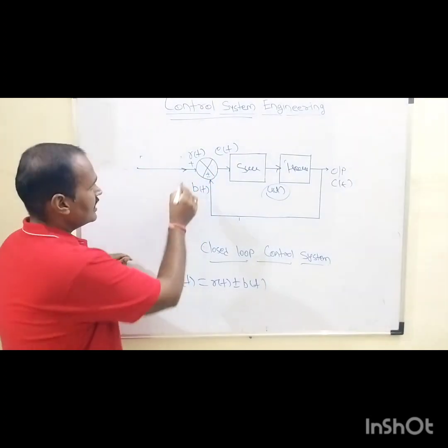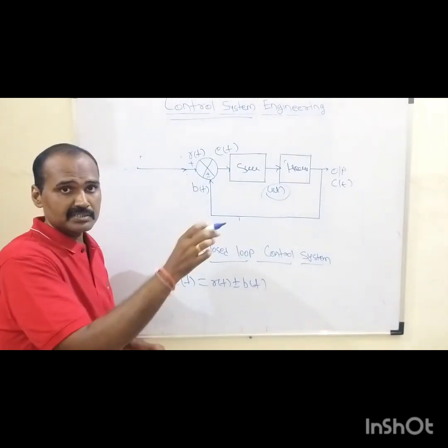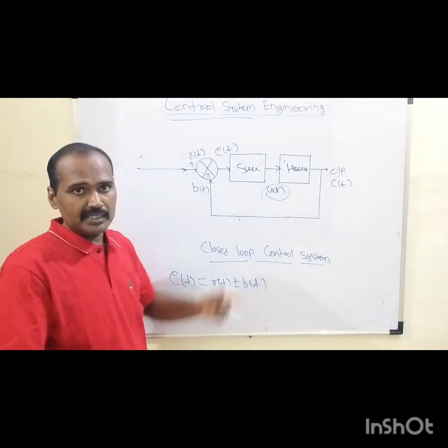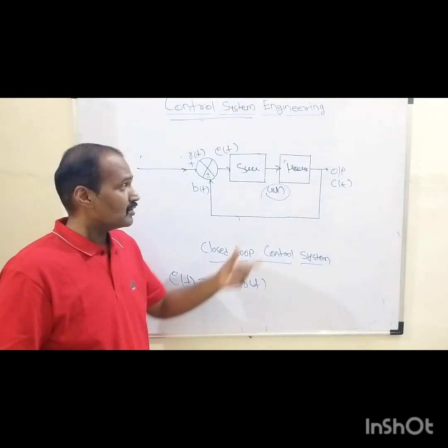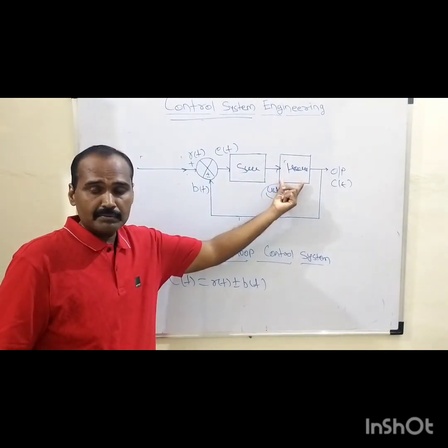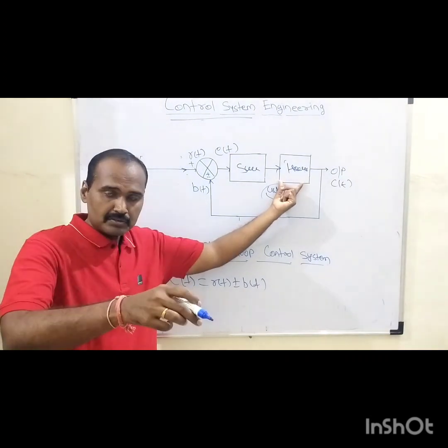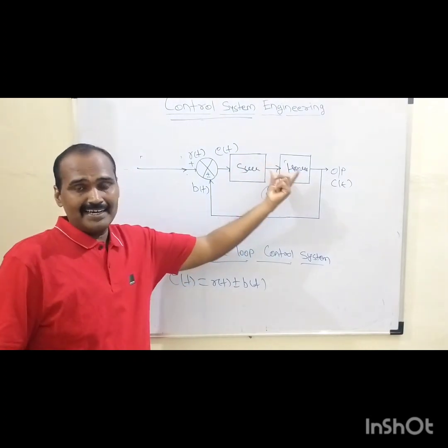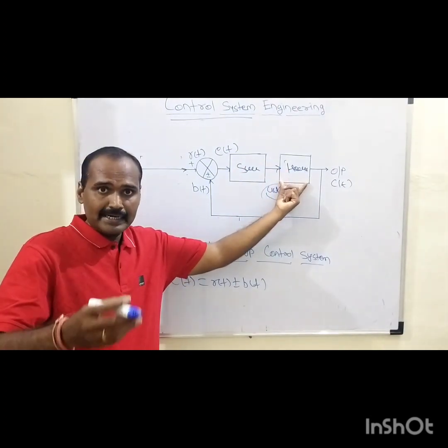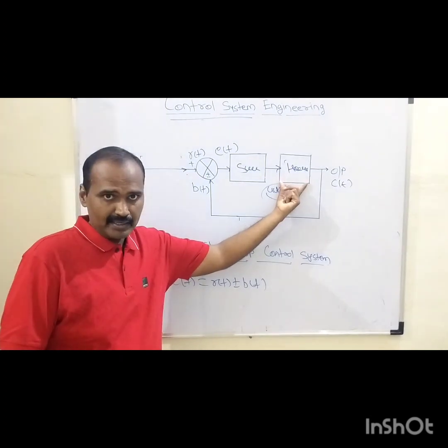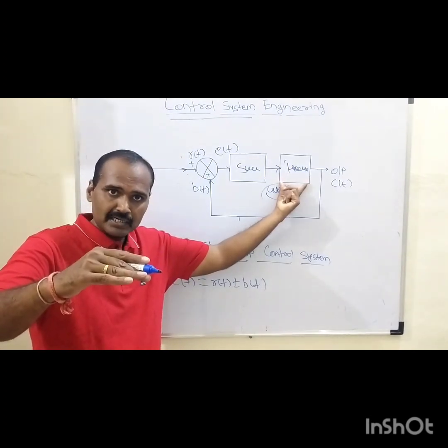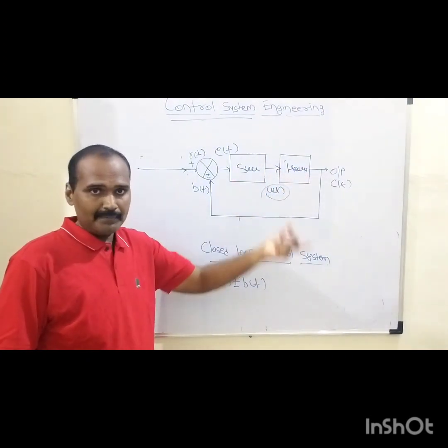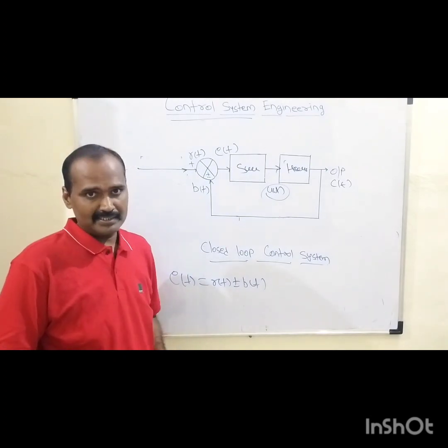Once the desired temperature is given, the role of this thermostat is to monitor the temperature of this heating coil. If the temperature of that coil decreases below that threshold value, then what will happen? This switch will be turned on and it will try to maintain the desired temperature by turning on that heater. If the temperature reaches the desired level, obviously this switch will turn off that heater, right? So each time some sort of feedback is being given into that system.